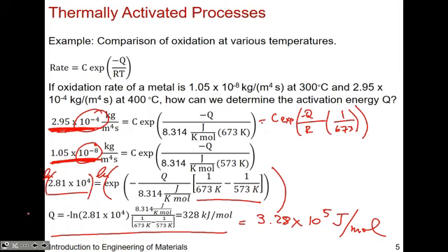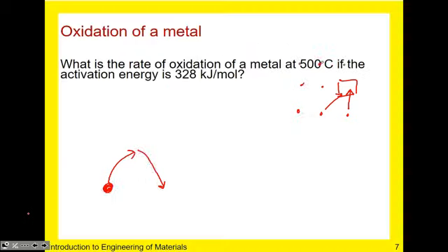So it's a huge increase even though you've just gone up 100 degrees Celsius, right? So you could think about, well, what happens when we increase temperature when we're trying to carburize, right? And you want your rate to be faster, just increasing the temperature a little bit will actually get the rate to increase by a lot. So you can get your carburization done in a much faster time than if you had sat at a lower temperature, okay, in terms of processing.